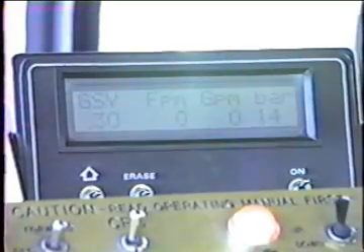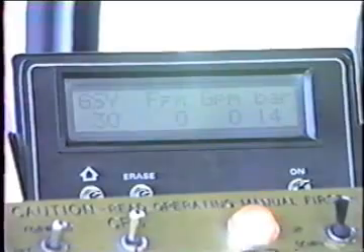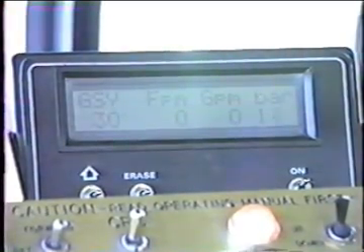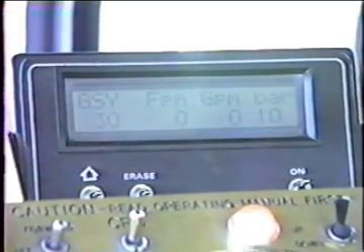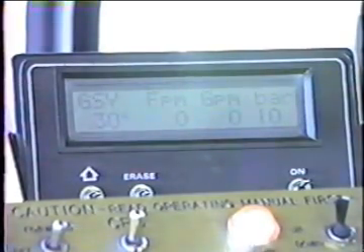And so it's going to supply enough asphalt for whatever it sees on the switches. If you have a wing up, be sure that you turn it off. Now we just have 10 feet. Let's say that we put down the inside wing on the right hand side, then we've got 12 feet. Again, just be certain you don't have switches turned on for a wing that's in that position.